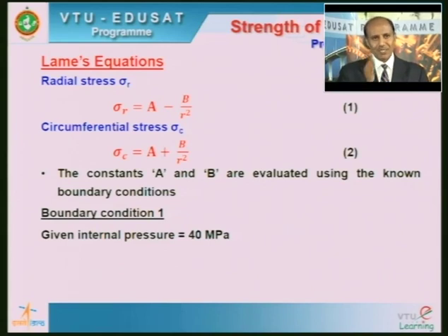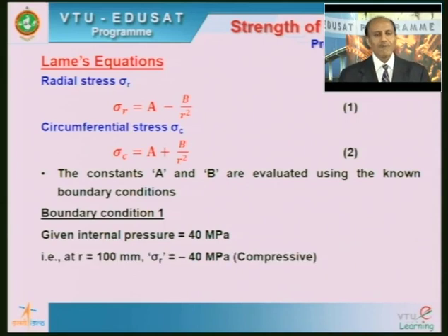Radial direction, correct. So this statement should be understood as the value of sigma r being 40 megapascals at the internal surface, where r is 100 millimeter.